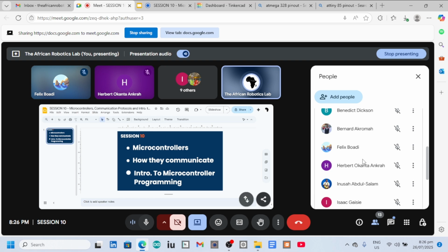So you use a voltage regulator to step down voltage. If you have a 9-volt battery but you want 5 volts, all you have to do is just connect that 9-volt battery to a voltage regulator. And the voltage regulator is going to step down that voltage to an output voltage of, let's say, 5 volt or 3.3 volt, that output voltage that you want. So that was voltage regulators.